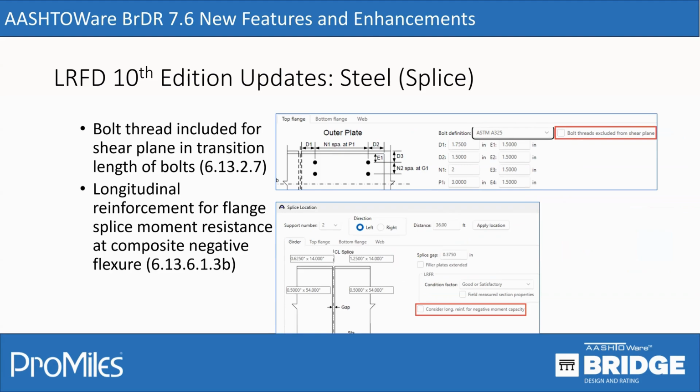Some other 10th edition updates are related to splices. There was an update to consider the bolt thread included in the shear plane in the transition length of bolts. So a checkbox was added to the splice window here. Essentially, this checkbox can override the option that is selected for the bolt definition. You may have a bolt definition that you're using for cover plates as well as in splices, but for the splice you want the bolt definition to behave differently for considering shear.